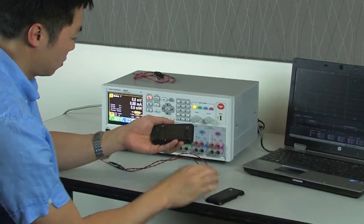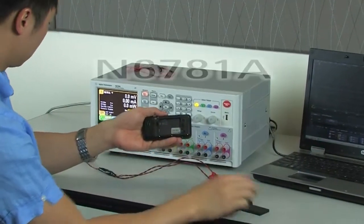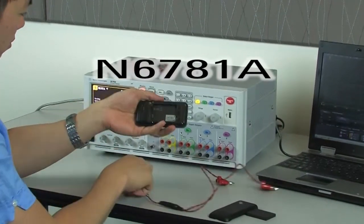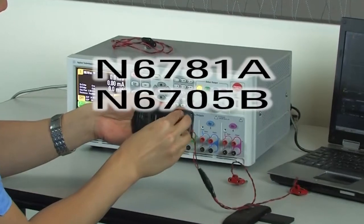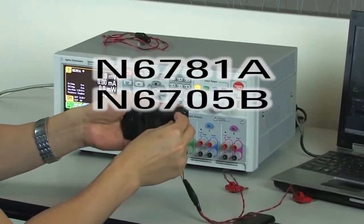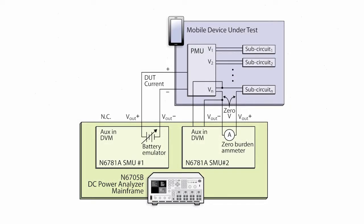There is a better measurement solution from Agilent Technologies for making these challenging measurements. The Agilent N6781A source measure unit installed in an N6705B mainframe has specialized features for testing battery-powered mobile devices. Here you see a test setup using two Agilent N6781A units to test a GPS device. One of the units was connected to provide a battery input, and the other was used to measure the RF amplifier subcircuit voltage and current.